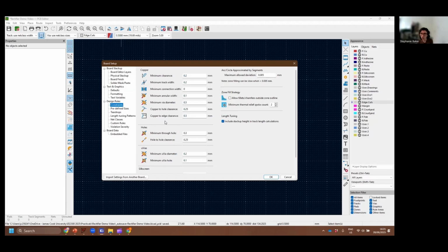Like we can get quite small parts and everything else, and that'll all come out beautifully. When we're working with an in-house mill, it can be a little bit more varied depending on the exact mill that we're using. So it's a good idea to increase our tolerances a little bit, just to make sure that we're not going to end up with stuff that's sort of shorted out or stuff like that, just because of the size of our drill bits type thing.